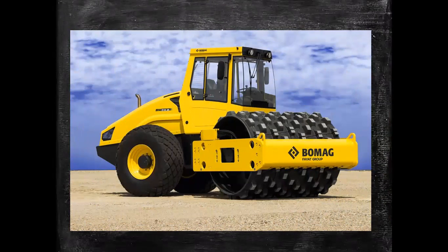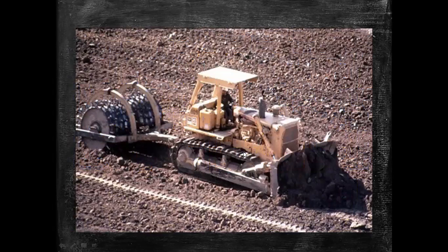With the sheep foot rollers, here you can observe this is the drum, which is fitted with the sheep foot knobs, so that it can compact the clay soils, and it is also useful for compacting any typical soils. This sheep foot roller drum weighs about 2 to 10 tons. And here you can see the sheep foot roller being used for compaction of the soil.